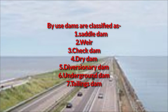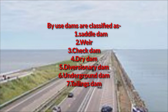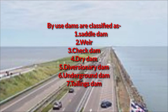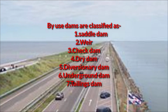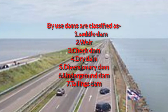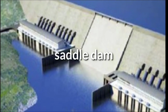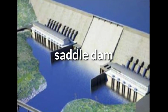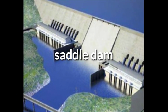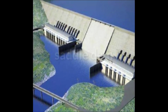By use, the dams are again classified as saddle dams, weirs, check dams, dry dams, diversionary dams, underground dams and tailing dams. A saddle dam is an auxiliary dam constructed to confine the reservoir created by the primary dam, either to permit a higher water elevation and storage or to limit the extent of the reservoir for increased efficiency.